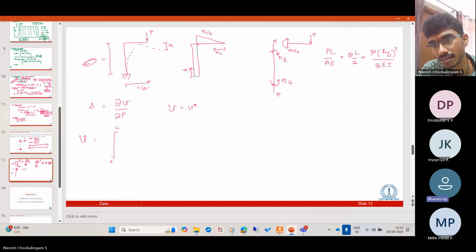So this will be the vertical deflection at that point. Okay, so what is theta? Theta is the rotation at this point. This works in this case. How do you find the rotation? Theta is equal to ML by EI. M is PL by 2, and the length is L, so theta is PL by 2 times L by EI.